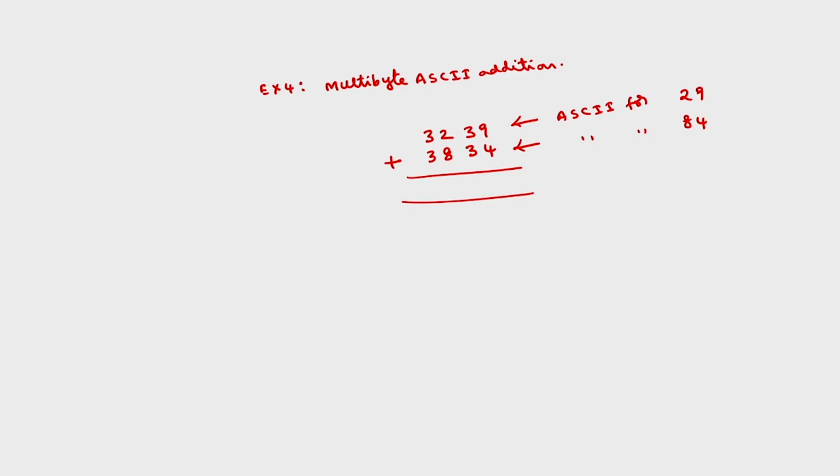As I already discussed while covering the ASCII instructions, 0 is nothing but 30H. If I press the 0 key on an ASCII keyboard, internally 30H will be generated, simply by adding 30 to that key. 1 means 31, 2 means 32, and so on up to 9 means 39.